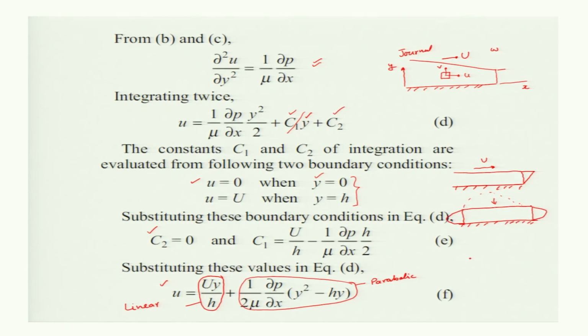And we considered that when there is a wedge type of action, or an inclined plate moving with surface speed U, the velocity of fluid can be obtained by the summation of this case and this case, equal to this one. So the velocity of fluid in this case is just analogous to our bearing system.